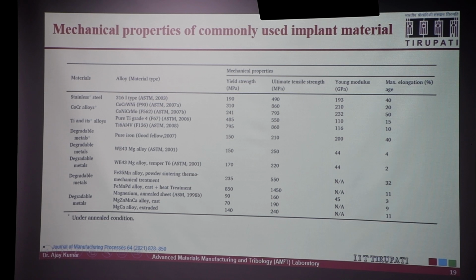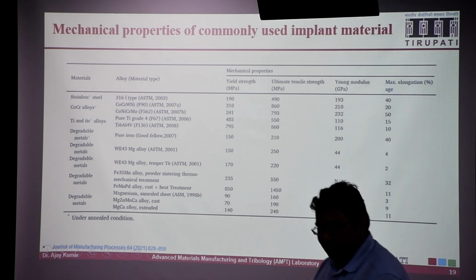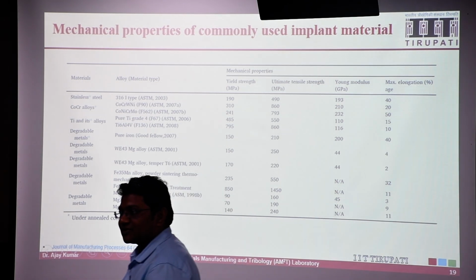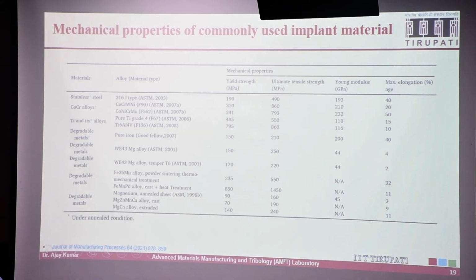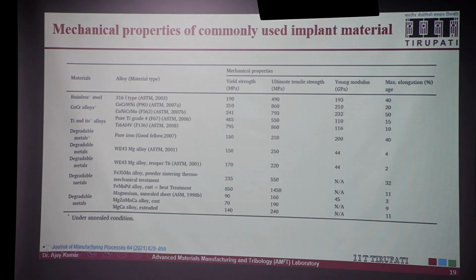So when we discuss the mechanical properties, all of you are aware of mechanical properties like yield strength, UTS, ultimate tensile strength, right? You also need to understand the fracture toughness, and then the compressive behavior, compressive strength. So basically when you apply the load, the material will experience tensile as well as compressive loading, isn't it? So the material is going to have fatigue loading also. So you also need to check the fatigue loading. Okay, so fatigue means cyclic loading, isn't it?